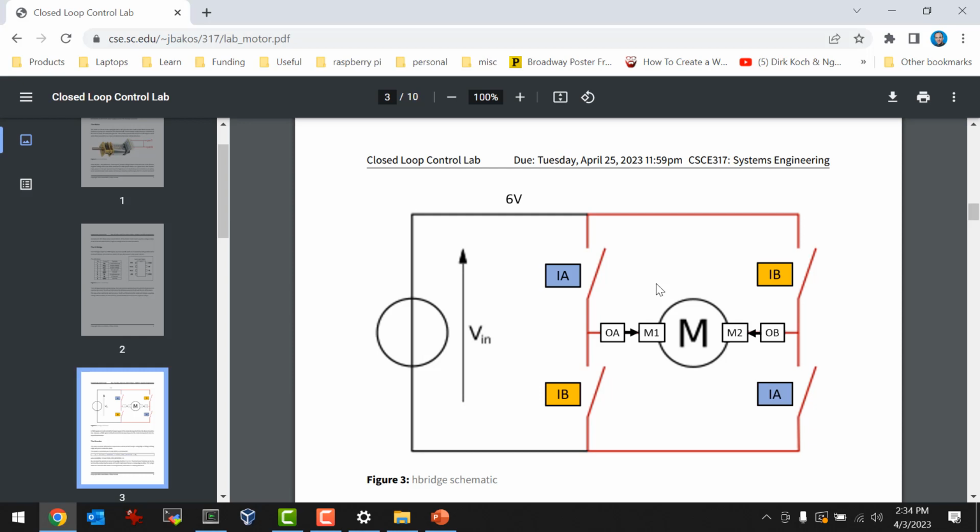And so the motor then, if you control the 2 transistors that are diagonal with a PWM signal, then what you're doing is you're basically turning on a path of current that comes down this leg, and then through the motor and then down this leg, right?